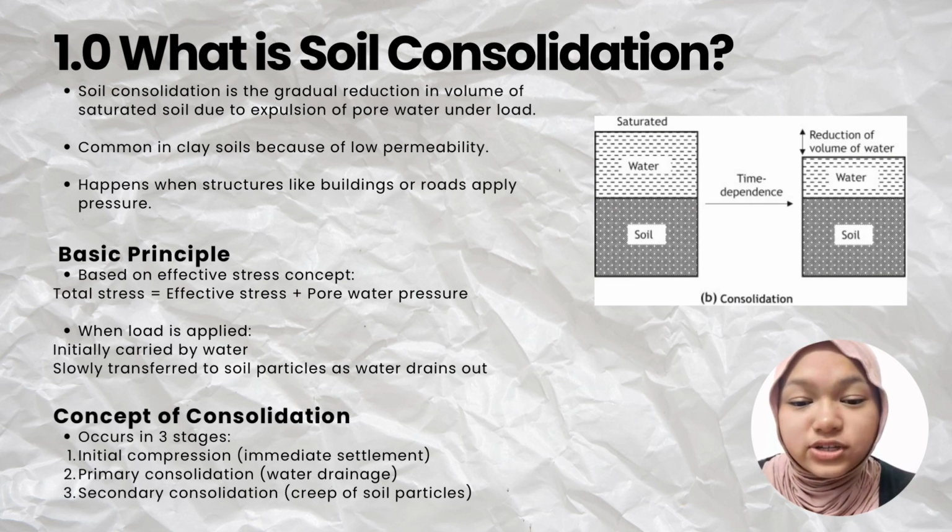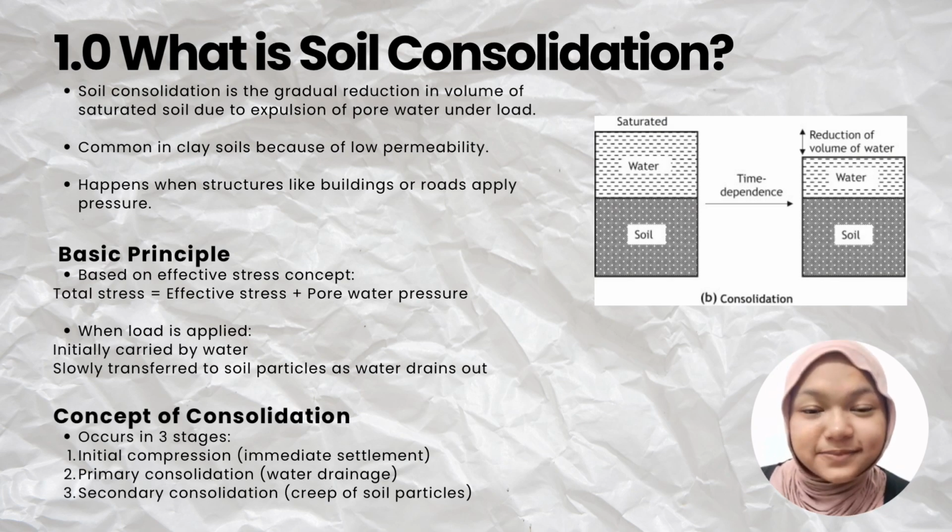Next, the consolidation process occurs in three stages. First, initial compression or immediate settlement. Second, primary consolidation, which involves water drainage. And third, secondary consolidation, which is the slow movement or creep of soil particles.